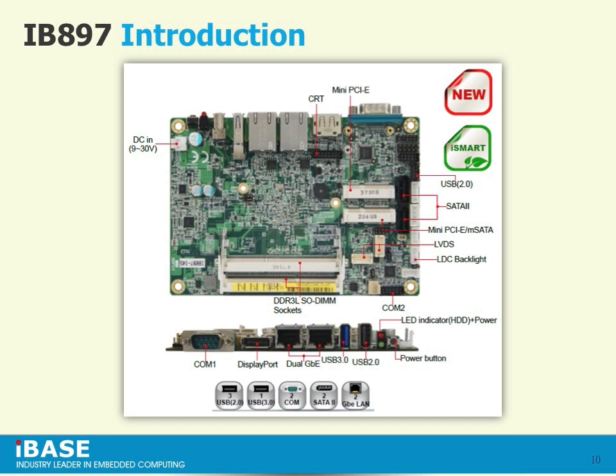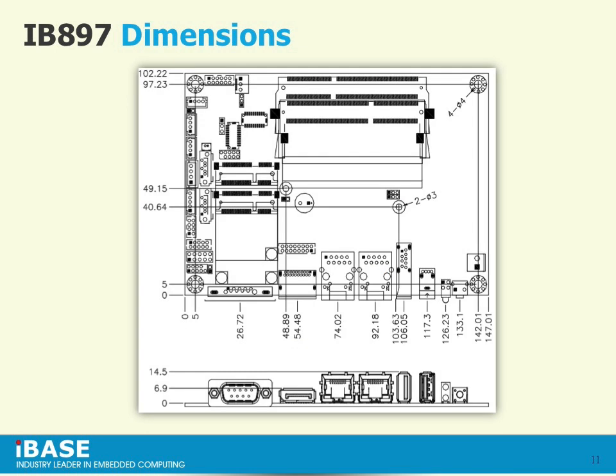You can choose the mSATA, and this board can fit mSATA very well with no problem. Also you will find there are 2 LVDS, the white connectors. There is 1 pair of this kind of connectors, so you can connect with the LCD panel through the LVDS connectors.